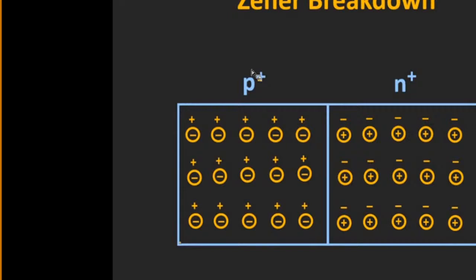The Zener diode is going to operate only in reverse bias. In the forward bias, it looks like a normal PN junction diode, but in the reverse bias, it acts as a voltage regulator. Even though the input voltage varies, the output is produced constant. Whatever stabilizers we see nowadays, there we use Zener diodes. The Zener diode is nothing but a constant voltage regulator. That we will see here.